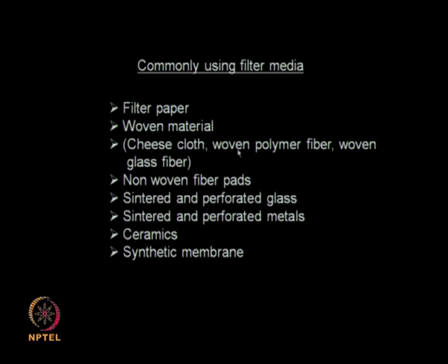So all these materials are being used currently. Some of them are very inert, they can withstand very high temperature, they can take in abrasive materials, they are long lasting; some of them are short lasting, so you need to replace these filter media. So the cost of your filtration, the working capital I would say, depends on how many times in a year or month you replace this filter medium.